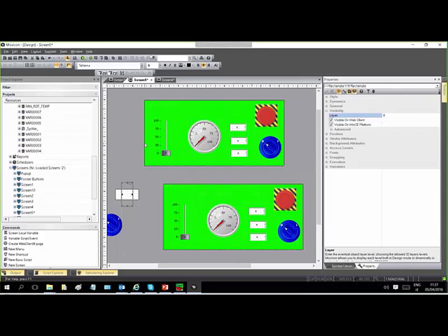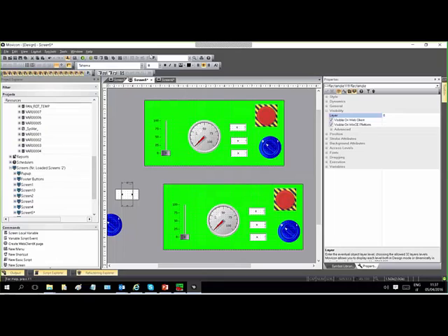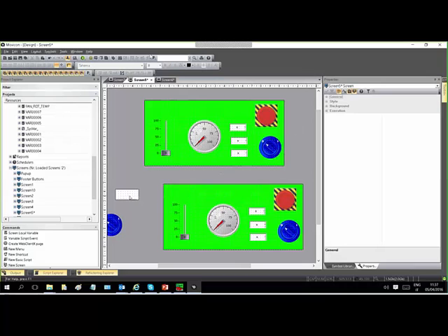Looking at different layers is a concept that I have not told you, but in Movicon screens, in edit, each screen has up to 16 different layers, so you can put your object in a specific layer, and in this way play with the visibility of the object. Even if it's not so used, because there is a very useful visibility property in the dynamic properties of the object.